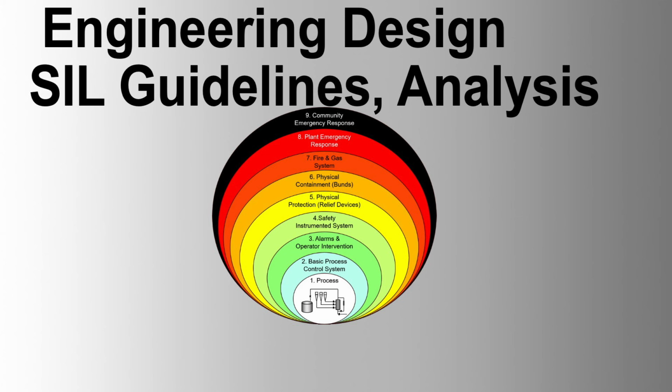6. Redundancy and voting configurations. Redundancy: using multiple components to perform the same function to improve reliability. Voting configurations. Systems can be configured in various voting logics like 1oo1, 1oo2, 2oo2, 2oo3, etc., to enhance fault tolerance.